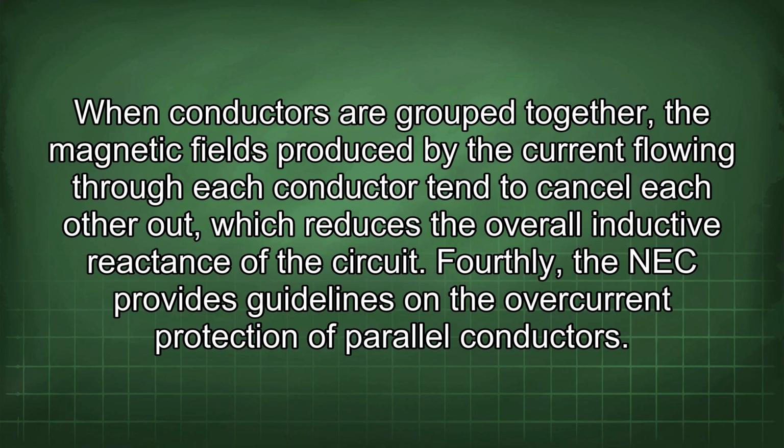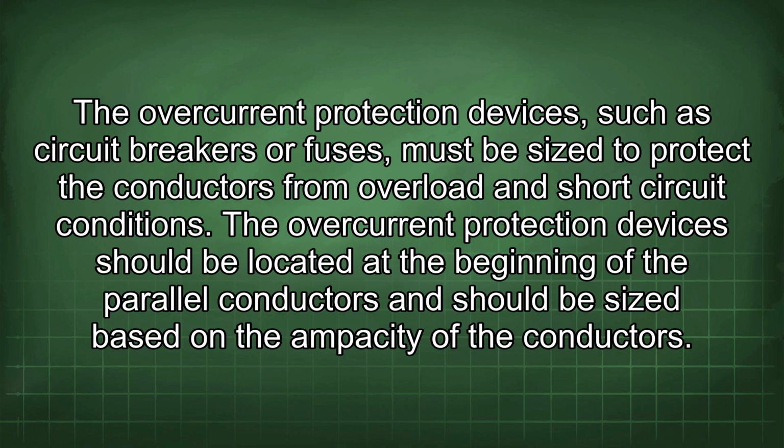Fourthly, the NEC provides guidelines on the overcurrent protection of parallel conductors. The overcurrent protection devices, such as circuit breakers or fuses, must be sized to protect the conductors from overload and short-circuit conditions. The overcurrent protection devices should be located at the beginning of the parallel conductors and should be sized based on the ampacity of the conductors.